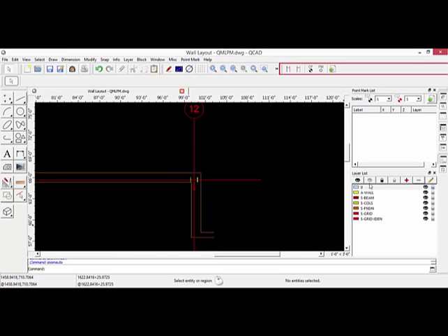Here's the layers that came in with this drawing. Now this is going to be different from the drawing that you have. You have a different drawing. So if I wanted to take a look at what we have, obviously I can click on a line, nothing there, nothing I can do with it right now. But if you want to take a look at what layer it's on, if you move down, you can actually see down here the selected entity says that it's on layer S grid. So now I can click on the S grid and change the information there if I need to. So how do we edit that information?